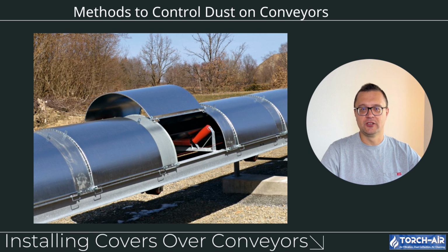Methods to control dust on conveyors. Now that we know where dust is generated, let's talk about the different methods we can use to control it. Installing covers over conveyors. One of the most basic yet effective ways to control dust is to install covers over the conveyor system. These covers help keep dust contained within the system and prevent it from becoming airborne.